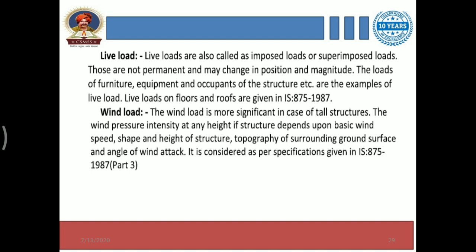Then it is considered as per the specifications given in IS 875 1987 part 3. Okay, these come in sequence: dead load in part 1, live load in part 2, and wind load in IS 875 1987 part 3. Okay, so these are some basic loads.